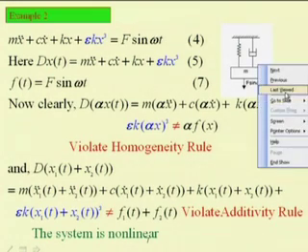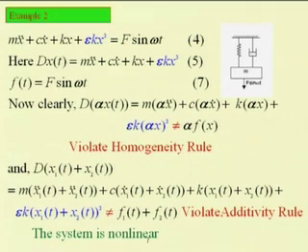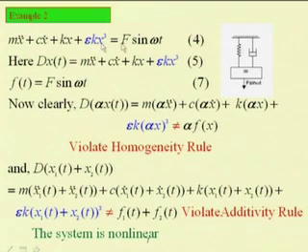In this equilibrium position, one can find whether the equilibrium position is stable, or whether it is unstable, or whether the equilibrium position is attainable or not. So we can study these equilibrium positions by finding the response of the system. The response of the system can be considered by studying this as a free vibration when the F sin omega t term is equal to 0, or it can be considered as a forced system when we are considering this force. So in the spring and mass system,